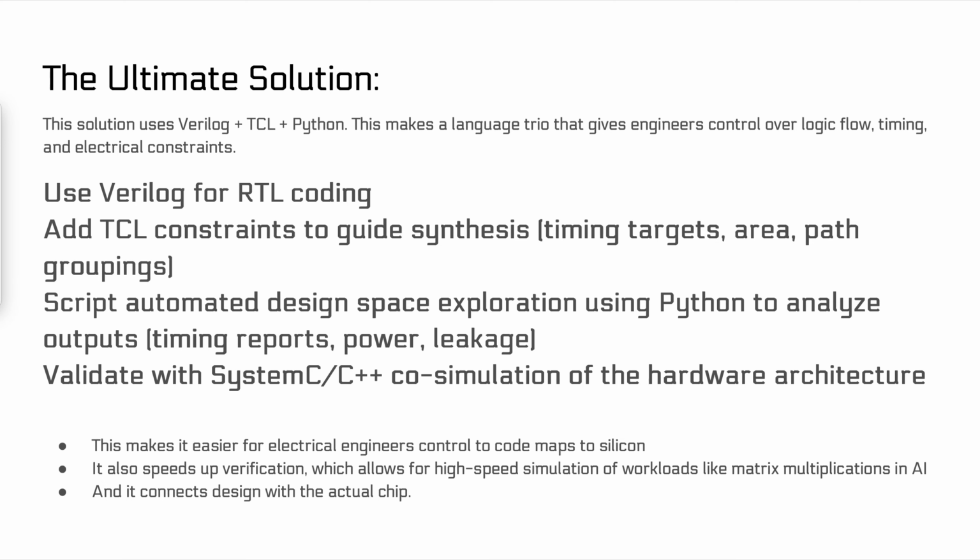Also, you want to script automated design space exploration using Python. And you do that to analyze the outputs. The outputs are the timing reports, power, and leakage in this case. And then once you've done that, you want to check this and test it. So I'm going to validate this with SystemC and C++. It's co-simulation of the hardware architecture.